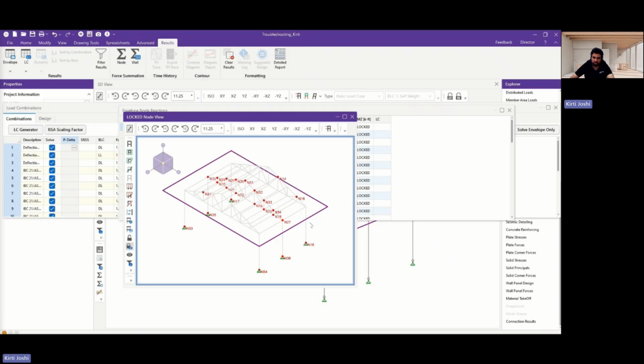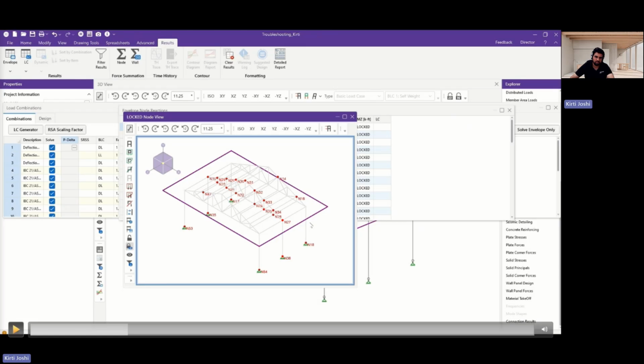These types of errors occur if the node has bending releases. We'll also see that to have a stable node, at least one member in the node must not have a release assigned to it. This is a similar concept to the instability, and it can be resolved similarly.